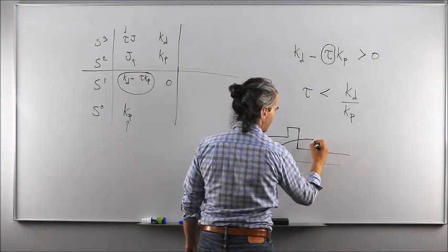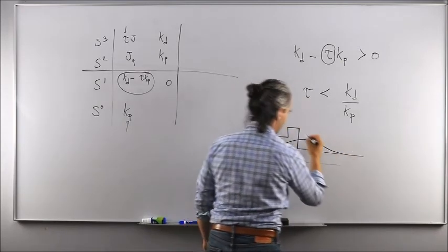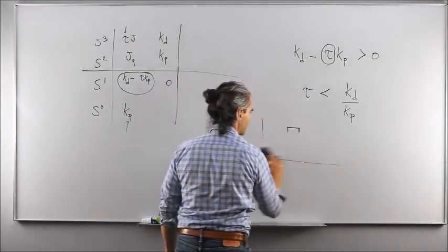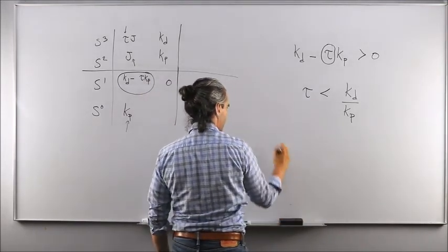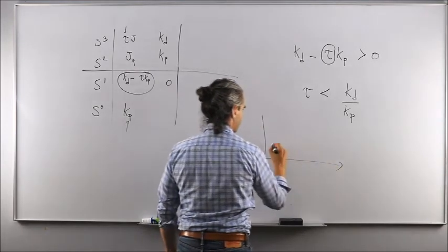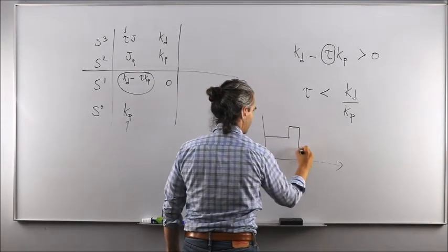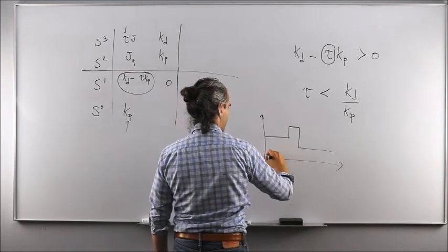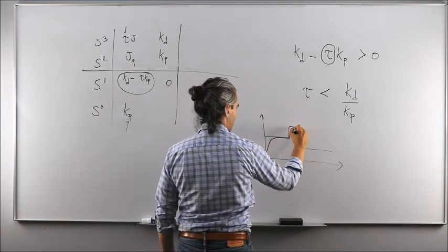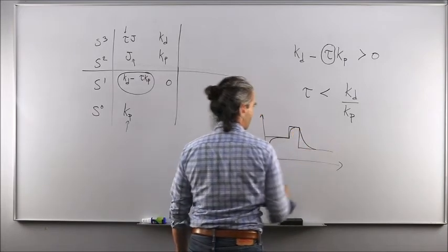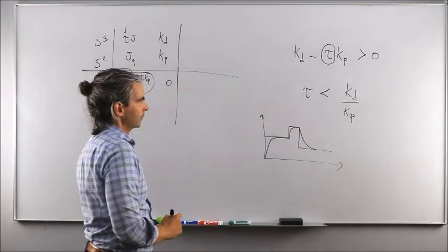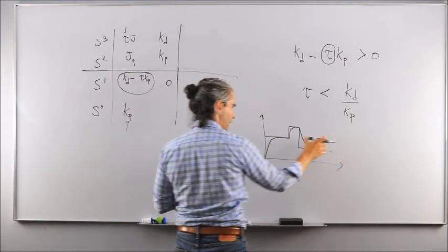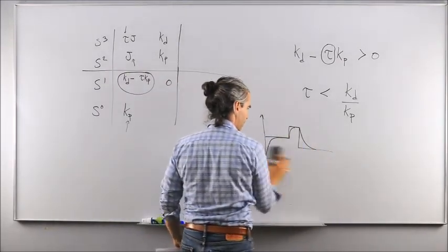It means that it would have neglected that one. So that would be a very bad actuator. It's way too slow to respond to what the controller wants. So a better actuator would be one that tracks the demand of the controller very quickly. Boom, boom, boom. Okay? That's way better. So the closer you can get the output of the actuator to match its input, the better.